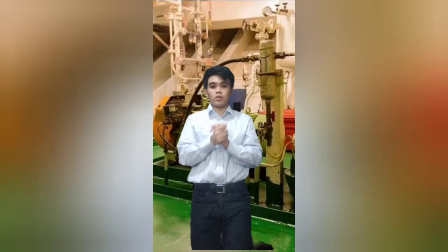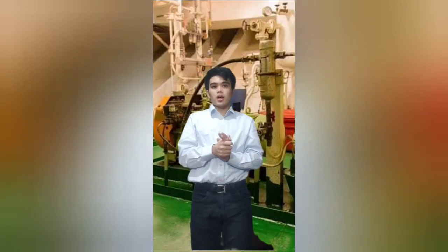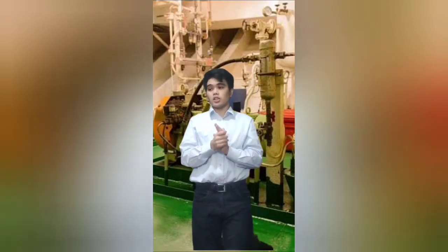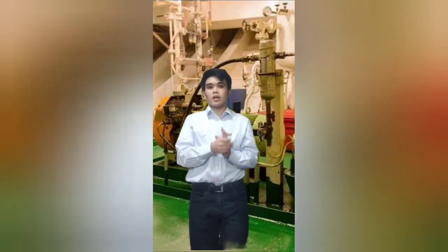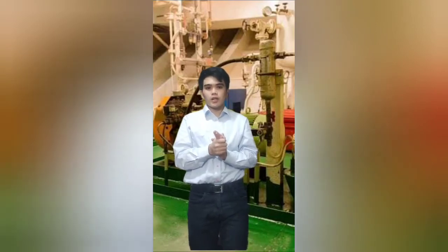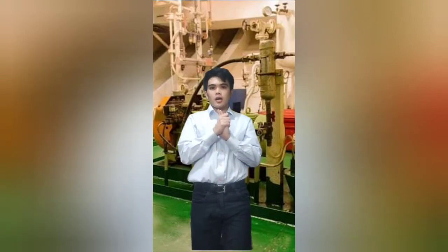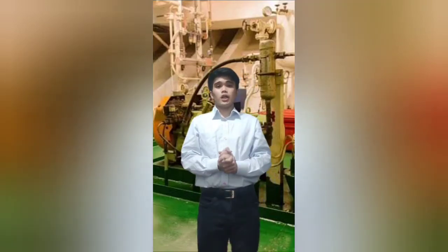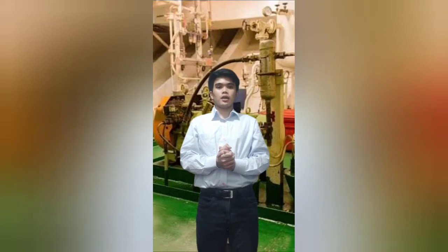This compressor has an axial flow, and the air or gas passes along the compressor shaft through the rows of rotating and stationary blades. The blades convert the kinetic energy to pressure, and a balancing drum is built in to offset the axial thrust. So that is the axial compressor.